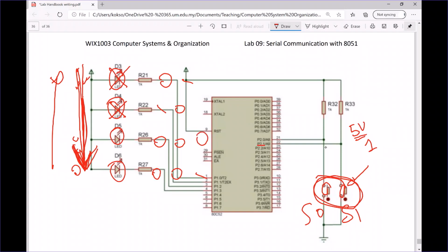Then it will reset to 1 0 0. So this one is off. So they are shifting in these directions, keep on looping in this direction, right? So this is basically a program to let you choose the shifting direction of the running LED. We call it a running light LED. The LED keeps on running.